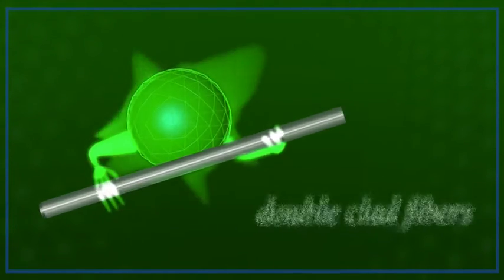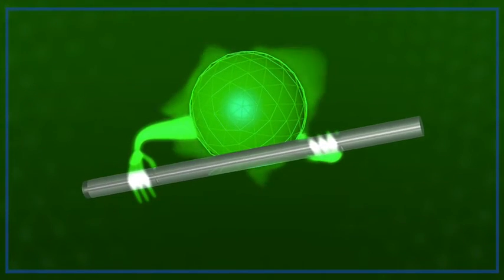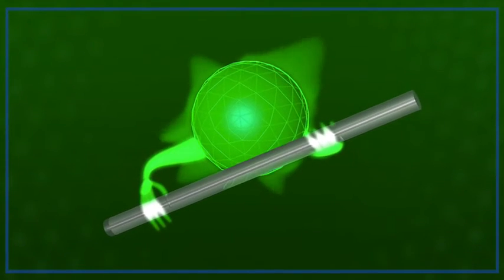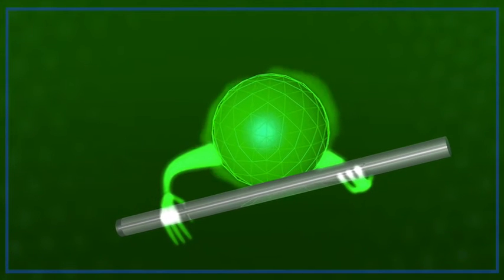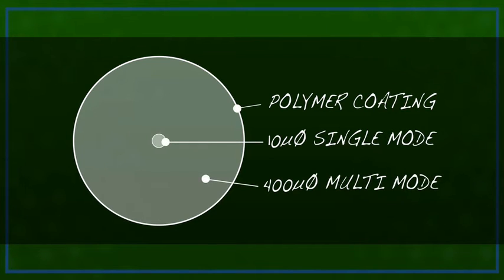Using these economical pumps requires the use of double-clad fibers. The invention of double-clad fibers enabled very high-power fiber lasers with good manufacturing economy, great electrical efficiency, and astoundingly high brightness. In principle, a double-clad laser fiber works the same way as the conventional fiber we just described.